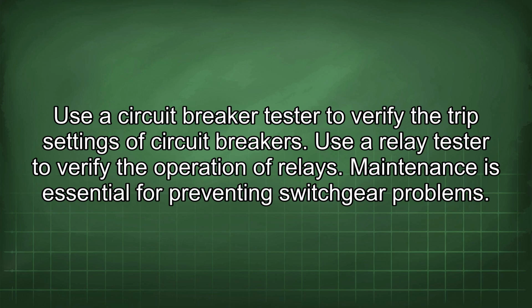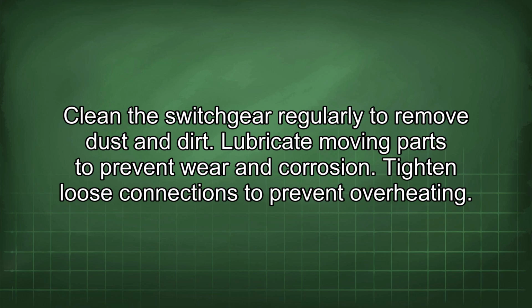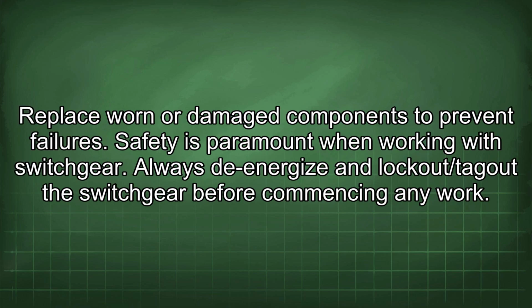Maintenance is essential for preventing switchgear problems. Clean the switchgear regularly to remove dust and dirt. Lubricate moving parts to prevent wear and corrosion. Tighten loose connections to prevent overheating. Replace worn or damaged components to prevent failures.